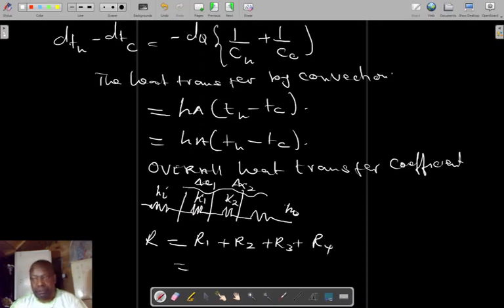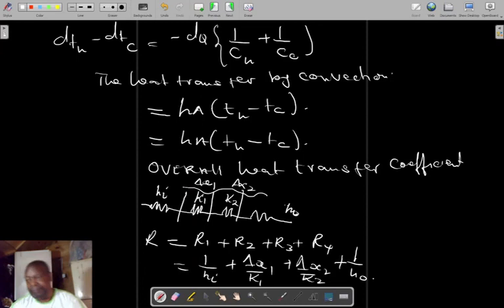So this is equal to 1 over hi plus delta x1 over k1 plus delta x2 over k2 plus 1 over ho.